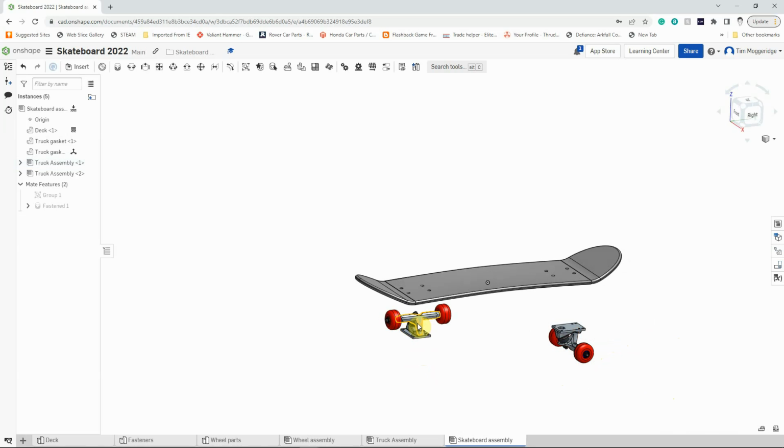So let's do the same on this one. Select it, spin it around 180 degrees so it's around the right way. Left click to clear it, left click to select it again, and this time I want to spin this one around 90 degrees this way. Haven't quite got 90 degrees, so type in 90, hit enter, left click to move it away.